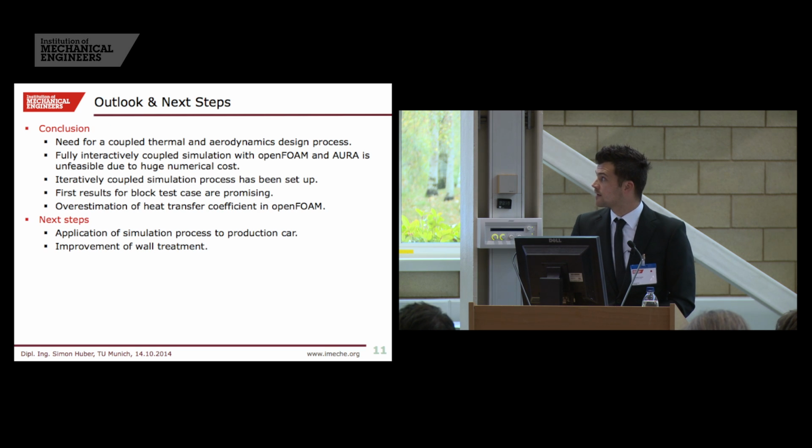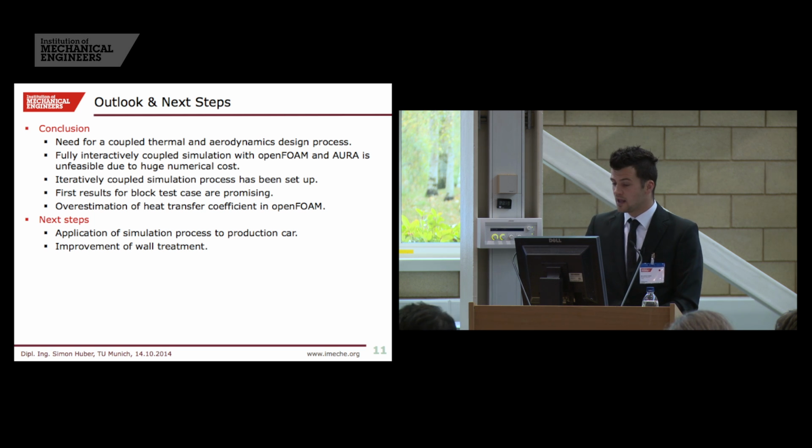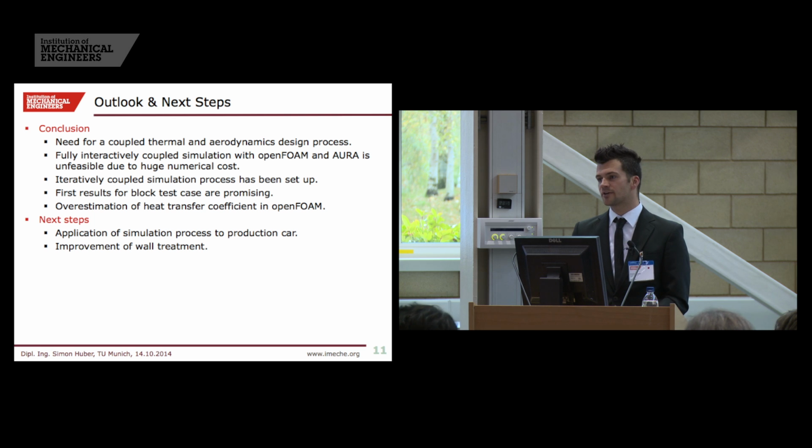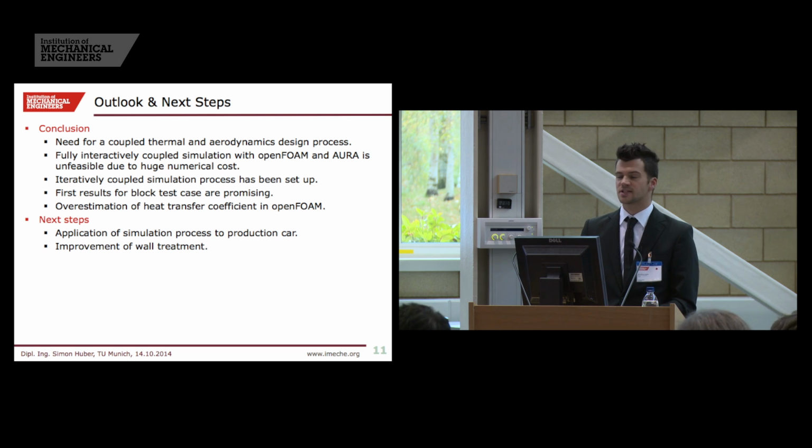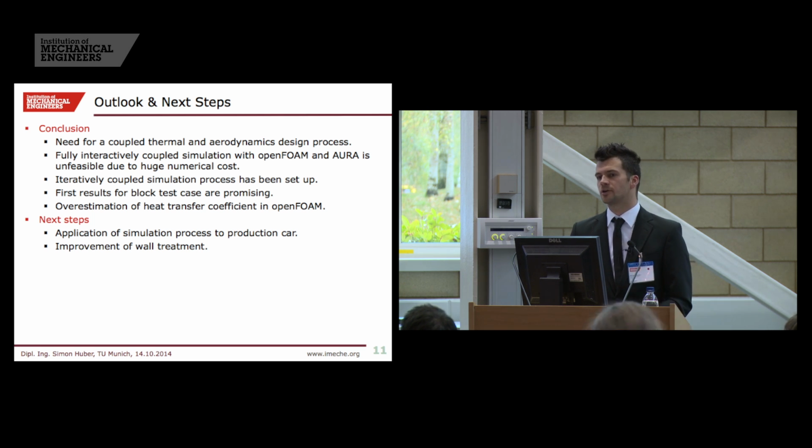So to conclude my talk, I have explained the need for a coupled aerothermal design process, but the fully interactively coupled simulation is unfeasible due to the huge simulation time. I have set up the iteratively coupled simulation process, and I have shown you some cooling curves for the block test case.